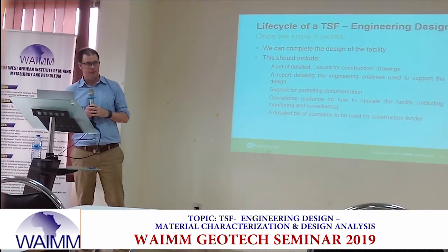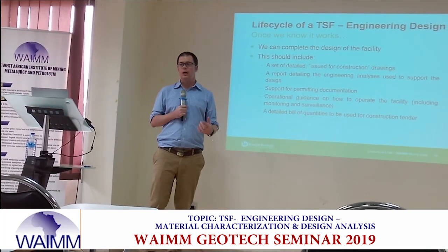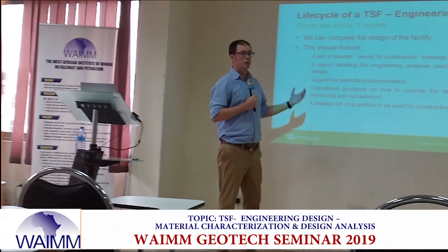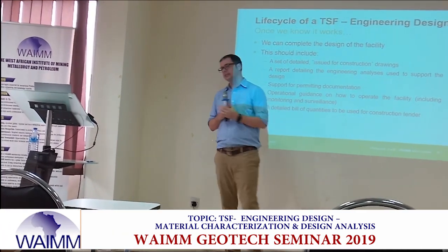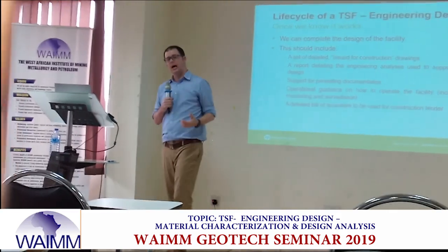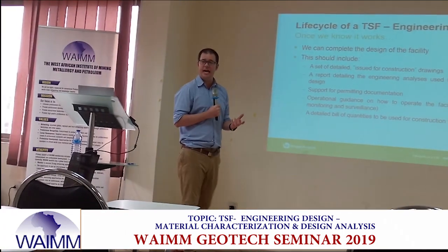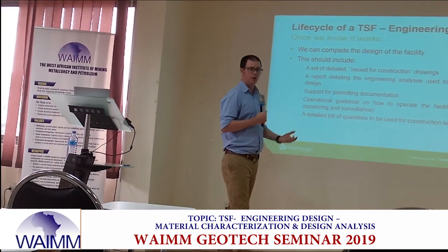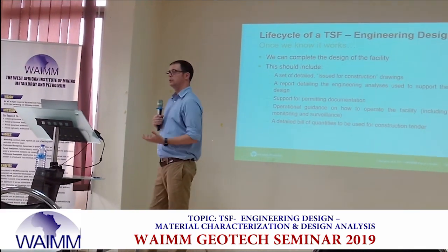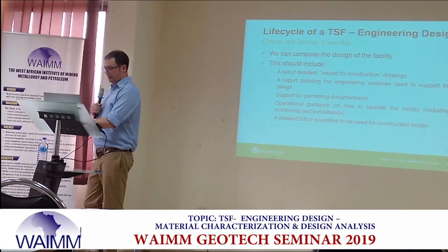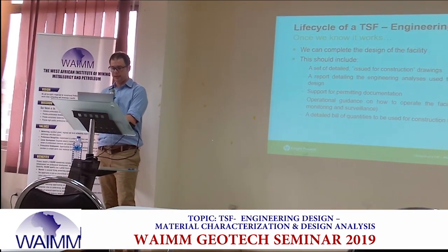The Mount Polley failure, for instance, in Canada, the reason it went from a deformation of an embankment to a catastrophic failure was that the operator had maintained the pond against the embankment. The facility was designed such that the pond was supposed to be maintained, I think, 300 or 500 meters away from the dam. Had the pond been that far away, we would have seen a deformation of the dam, but we wouldn't have had a release. And then we also need a detailed bill of quantity, the BOQ, for the construction plan.